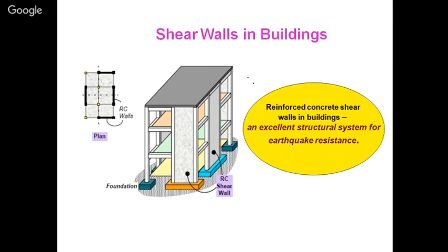Shear walls in buildings, that is, you are providing shear walls in buildings to participate in your lateral load carrying capacity. If you are providing shear walls into your design, so that your frame and your shear wall both are participating in the lateral load capacity, then in that case also you can decide what proportion you are giving your shear wall to be taking the lateral load. Most of the cases it is 70 to 30%, 70% shear wall and 30% your frame structure. That is the lateral load carrying capacity which the designers take.